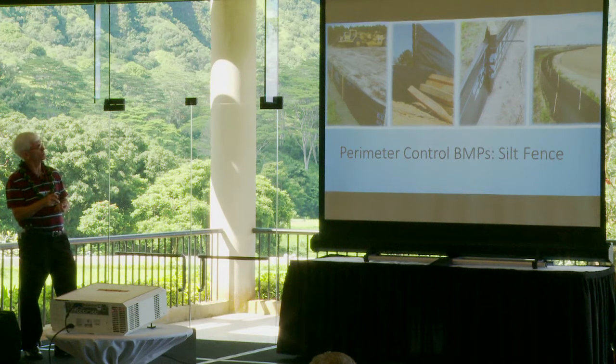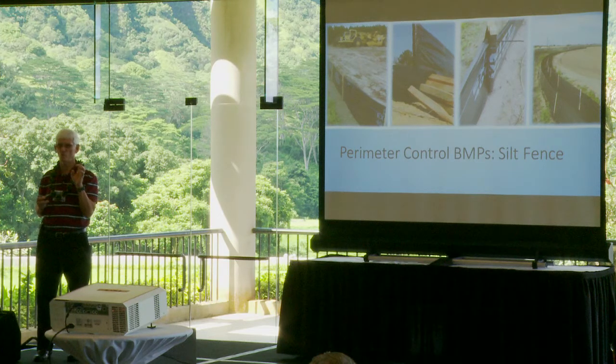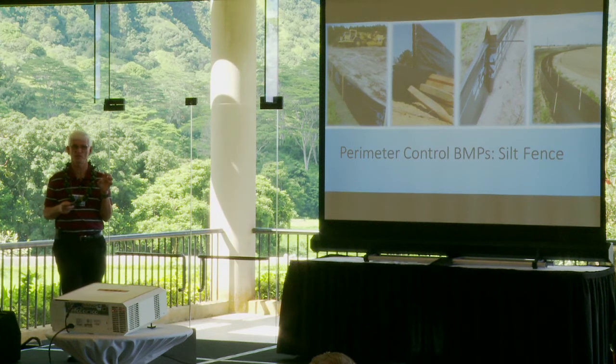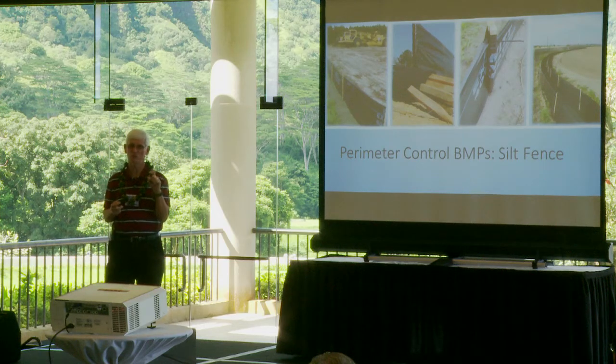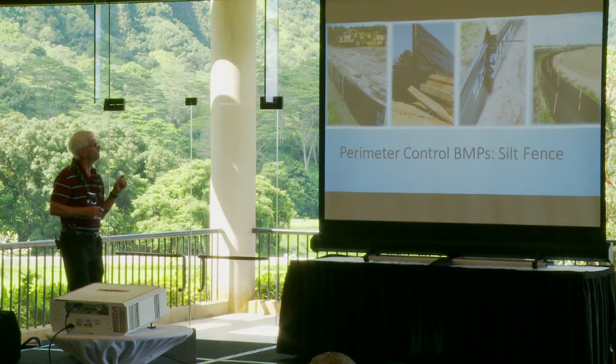Always make sure that the posts are on the downstream side of the flow, because if they're reversed, then the only thing you have holding up to the strongest force of nature, which is water, is staples, and it won't work.